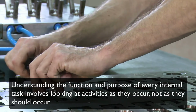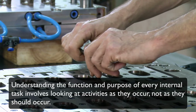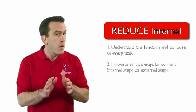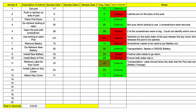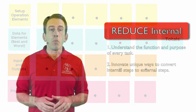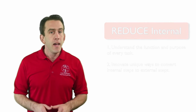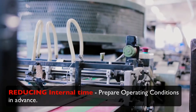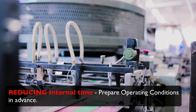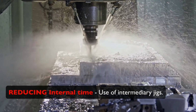Understanding the function and purpose of every internal task involves looking at activities as they occur, not as they should occur. Remember, you have taken a Gemba walk, gathered information, recorded the setup, and mapped the process out. This valuable information will allow you to look at the setup process in the current state. As you do this, you will likely find that these common techniques will help improve your internal setup. Prepare operating conditions in advance. Standardize essential functions and use of intermediary jigs.